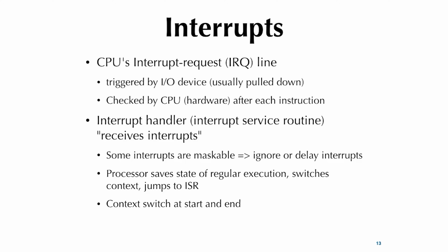And how does it do it? Well, does it set it to a 1? Well, no, most likely it sets it to a 0. It asserts it. It's what's called active low. So normally, if nothing is happening, it's left high, and there's usually a pull-up resistor pulling it high. And if it wants to make a request, it asserts it low. Okay, pulls down to 0 volts.